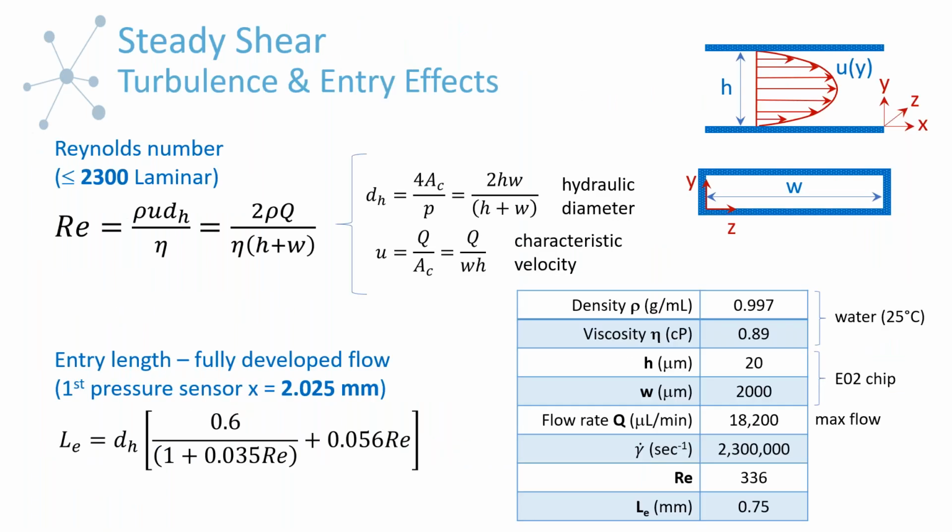Okay, so one of the other things I wanted to mention with respect to our channels and things that you might want to consider: we had mentioned that there are two things when you're dealing with the microfluidics or the rectangular slit geometry, which is different than when you're dealing with the rotational geometries. Reynolds number is still important in your other geometries, but because of the length scales that are associated with those, you tend to have more issues with turbulence in those geometries.